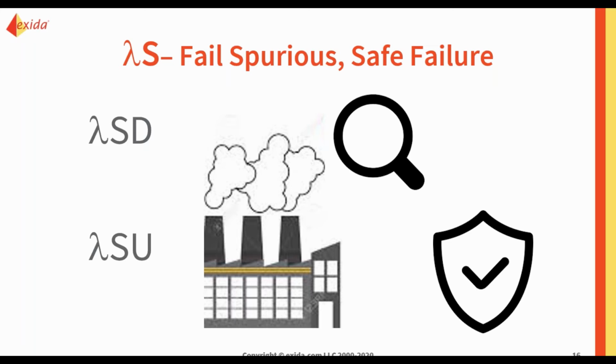Or what if you have an output fail open and it immediately goes to the safe state? With both of those, your process would be running in normal operating conditions, and depending on your internal diagnostics, if it caught it in time or not, you could be in a shutdown situation unnecessarily.